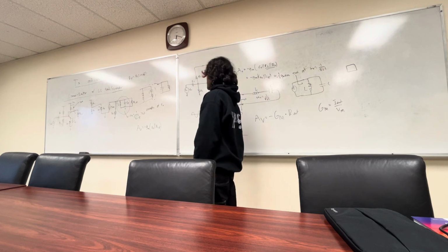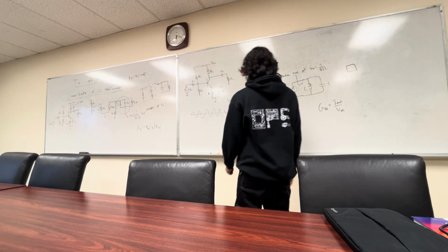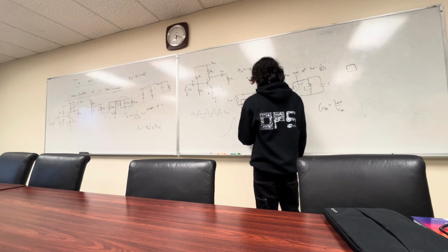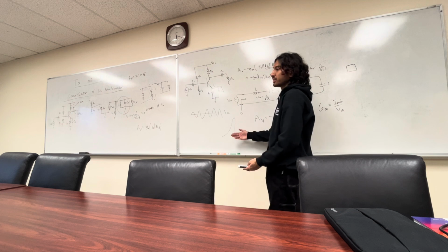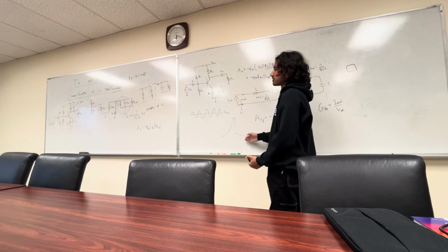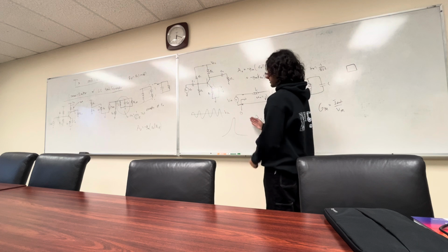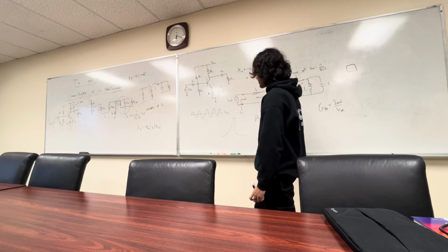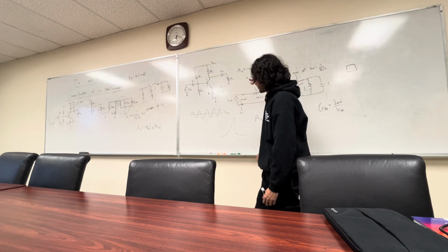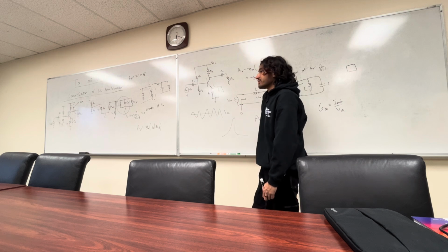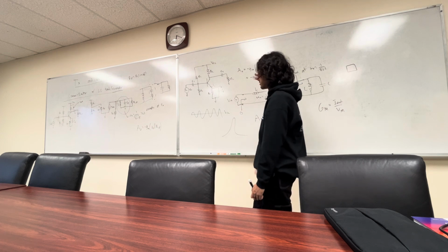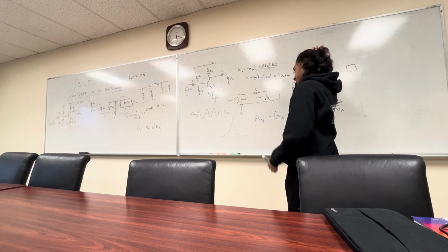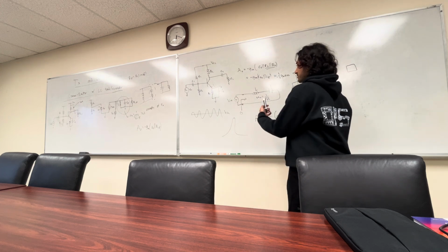And basically, if you have this phenomenon, other frequencies get attenuated. If other frequencies get attenuated enough, they can't oscillate at those frequencies, right? So that's the idea here. And I guess you see this in LNAs as well. That way, you can greatly limit other frequencies that come in, out-of-band frequencies, for that reason: for oscillation, for general saturation, as well as for noise performance.